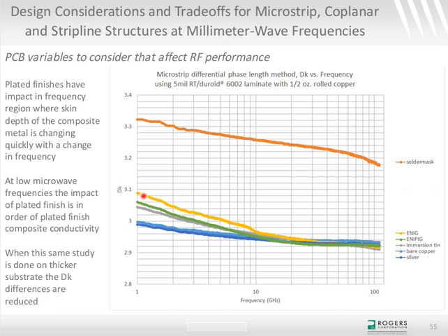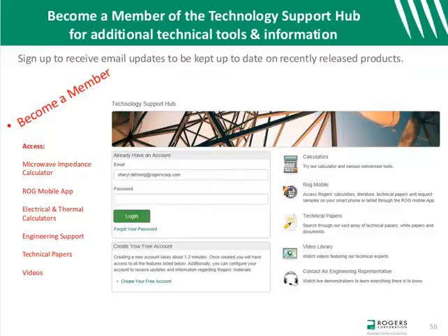response. And some of the problem there is nickel will change in thickness from one circuit to another, and the change in nickel thickness will actually cause that phase response to go up and down from one circuit to another. Now, at millimeter wave frequencies, what we're mostly talking about, you get to a thin enough skin depth where that's really not an issue, but I thought I'd throw it out as an FYI.